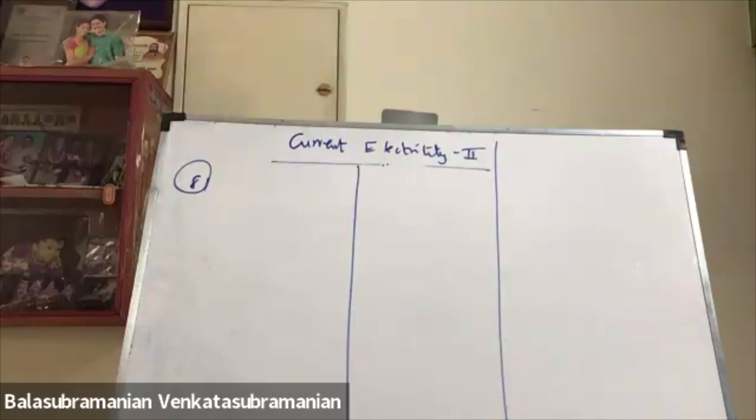of 3.2 ampere, which settles after a few seconds to a steady state of 2.8 ampere. Previously 3.2, now it is 2.8. What is the steady temperature of the heating element? Room temperature 27 degrees Celsius. Alpha value 1.7 into 10 power minus 4. You have to calculate T2.